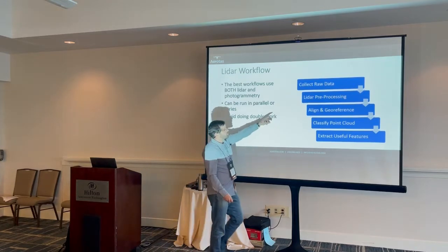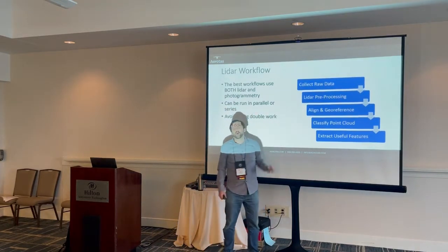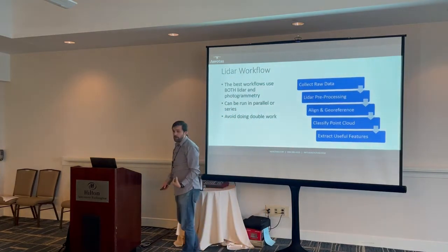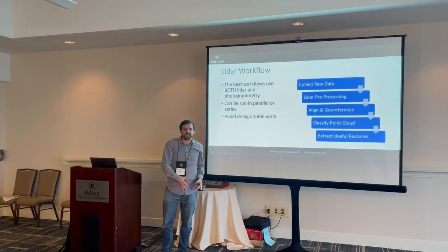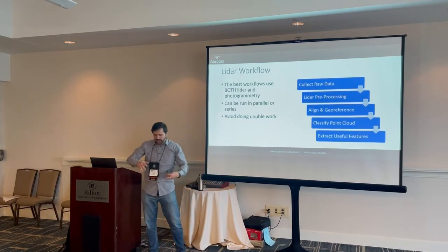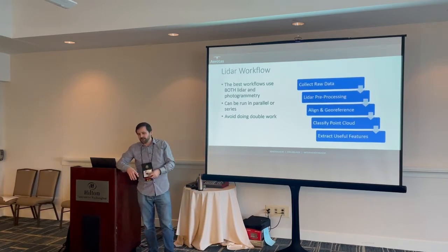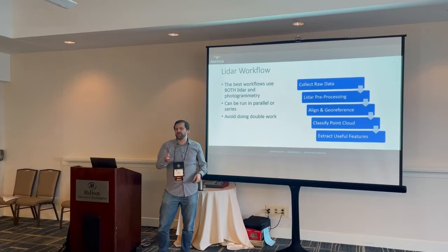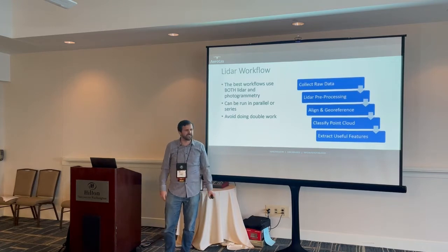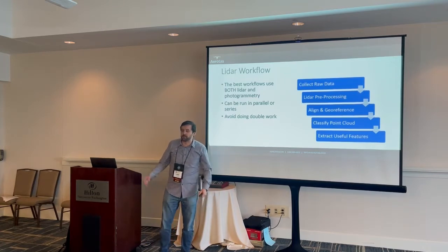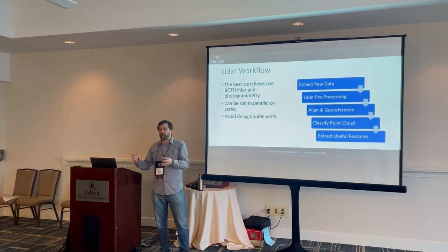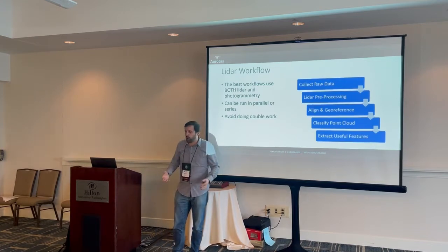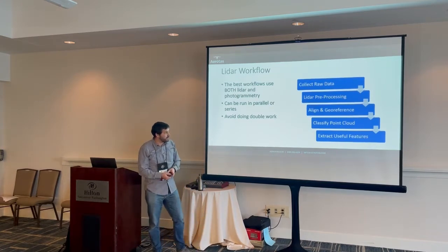This step, as we'll go into a little bit, is typically proprietary for each individual drone. So if you're working with the DJI L1, it has to be done through DJI's Terra software to create those point clouds. Various micro drones use their own software as well. I think it's based in something like Trimble Business Center, but basically it allows you to integrate other base station data and actually create a point cloud at all. Before that, you can't do anything.